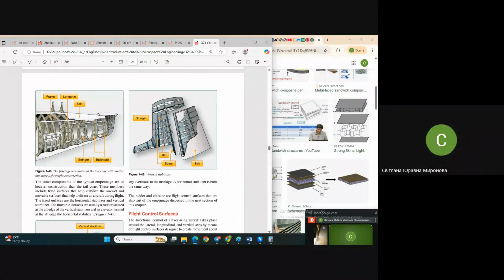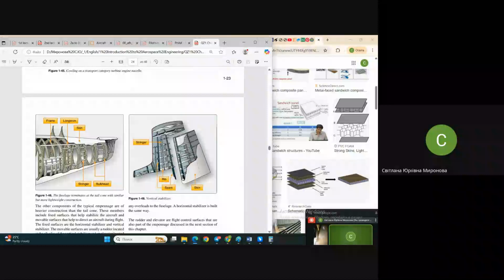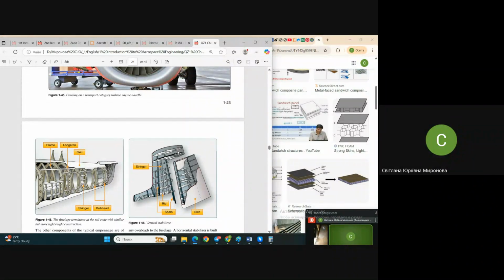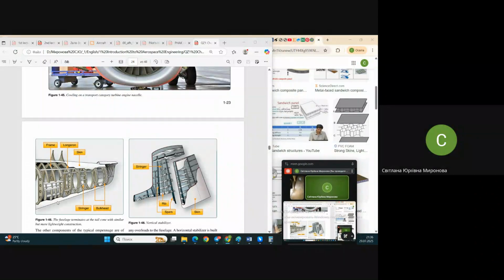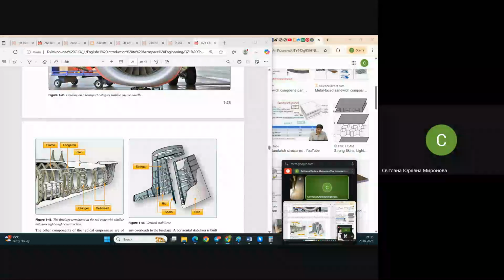Actually, these truss-like structures were like an inner truss surrounded with some envelope, or even without it. You might think the fuselage consists just of these pipes, not even covered with any additional elements like skins. Once again, I repeat the nomenclature of elements, and let's stop on this. The fuselage consists of frames and stringers: a semi-monocoque fuselage.